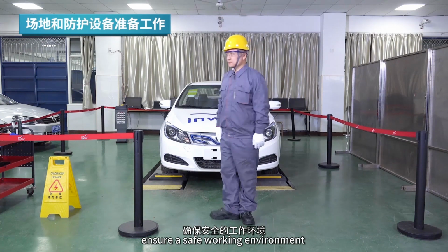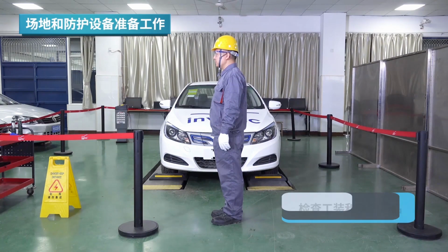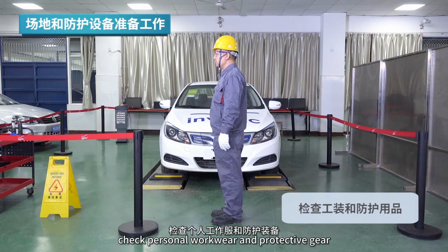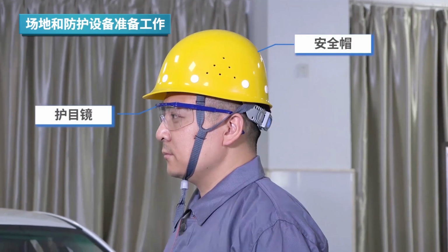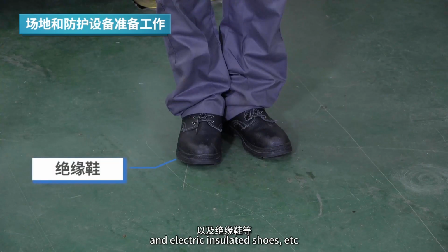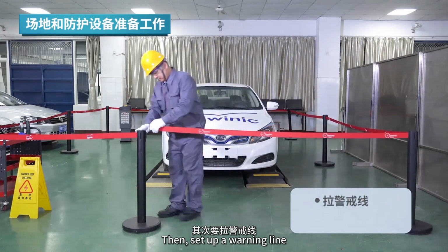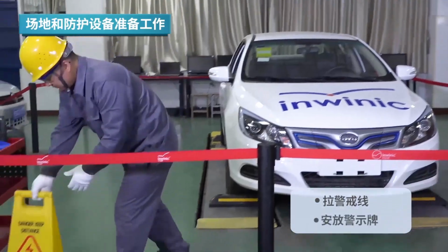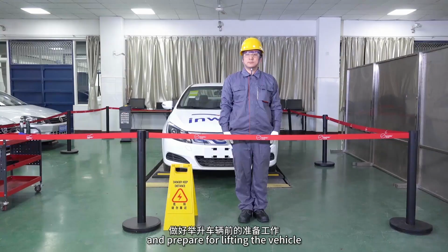First, ensure a safe working environment and prepare protective equipment. Check personal workwear and protective gear, including safety helmets, goggles, gloves, and electric insulated shoes and so on. Then, set up a warning line and place warning signs and prepare for lifting the vehicle.